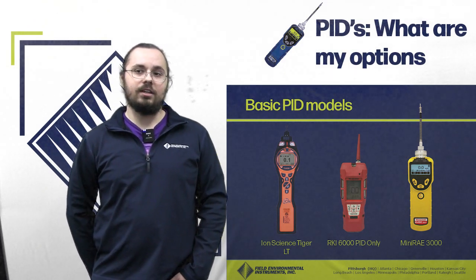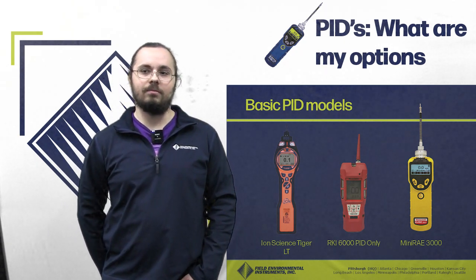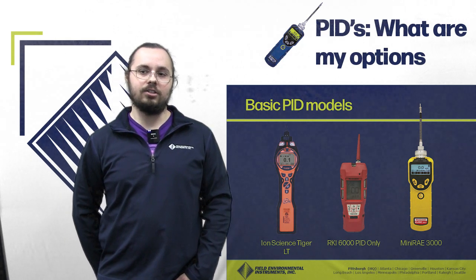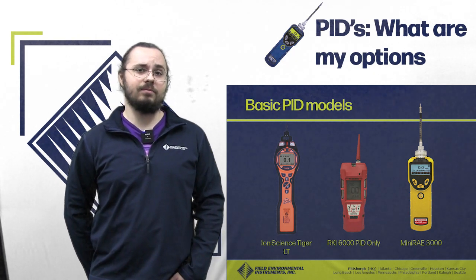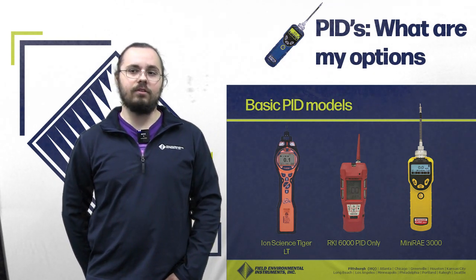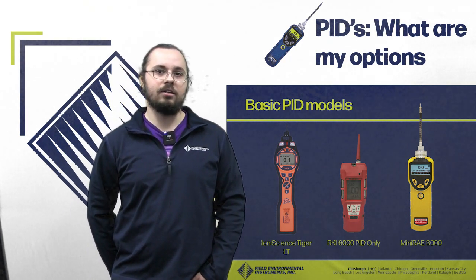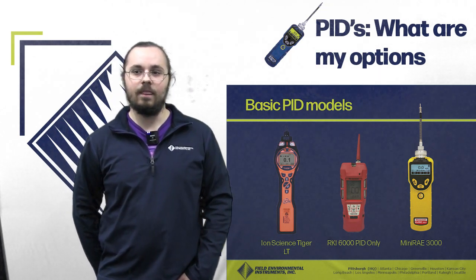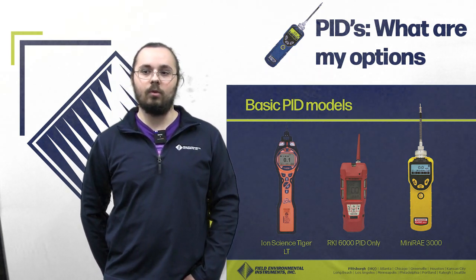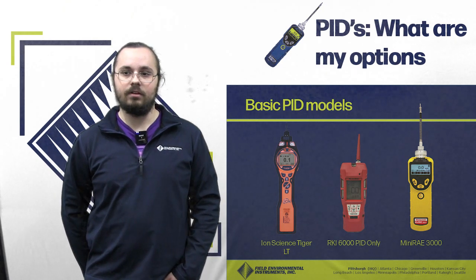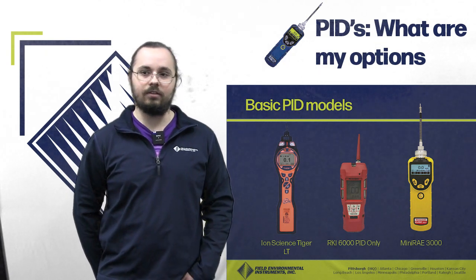The Tiger LT has a range from 0 to 5,000 ppm, a resolution of 0.1 ppm, has data logging features, and features a 10.6 eV lamp. The RKI 6000 PID, on the other hand, has 2 different forms of resolution. It has a low range from 0 to 50 ppm and a high range from 0 to 6,000 ppm. Resolution can be 1 ppb on the low setting or 0.1 ppm on the high setting. It features a 10.0, 10.6, or 11.7 lamp and also has data logging features.